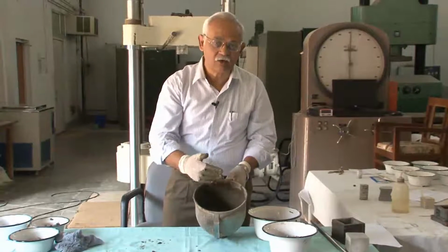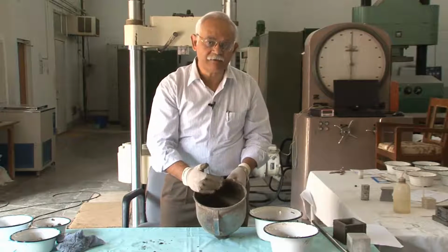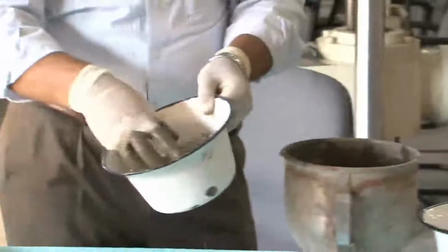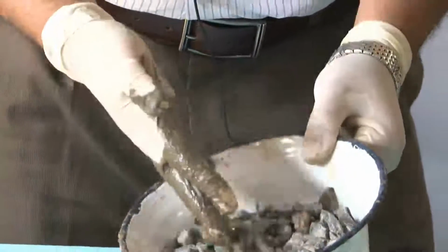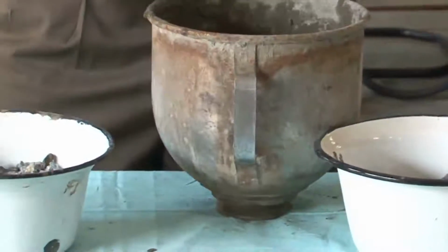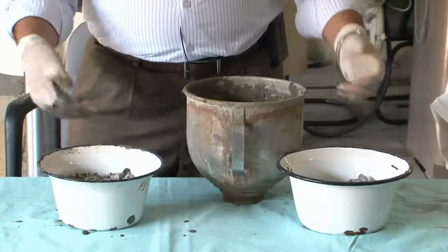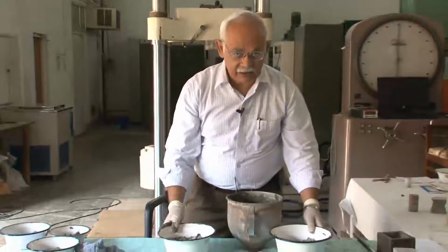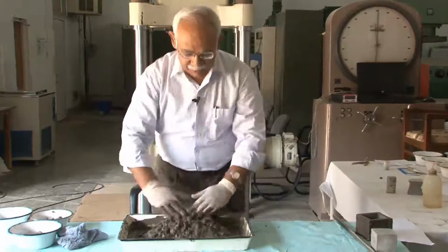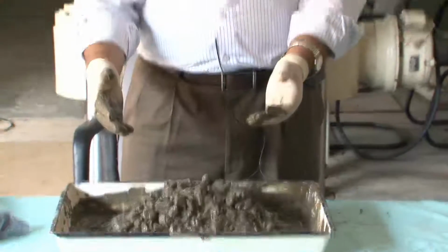Now, let us add coarse aggregate to this system, and what we will get is concrete. We are adding coarse aggregates of two gradations, the smaller version, which is about 10 mm aggregate, and a larger version, which is 20 mm aggregate. Both these size fractions are about 1.3 kgs again. So, let us add the coarse aggregate to the mortar and see what happens to the concrete. This is the concrete that has been produced by mixing 1.3 kgs of 10 mm aggregate and 1.3 kgs of 20 mm aggregate to the mortar, which had 1.3 kgs of sand added to a paste.